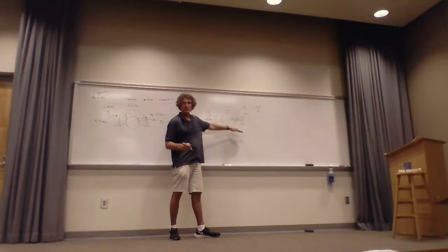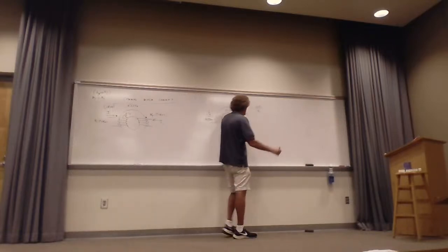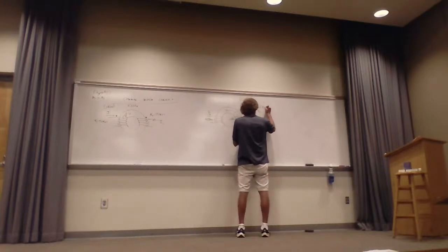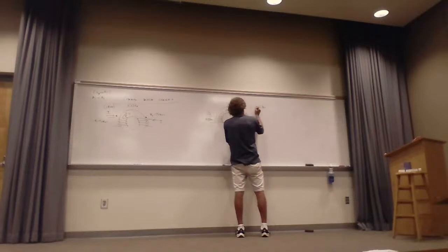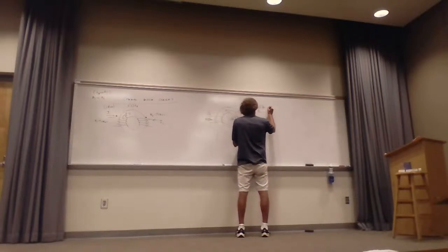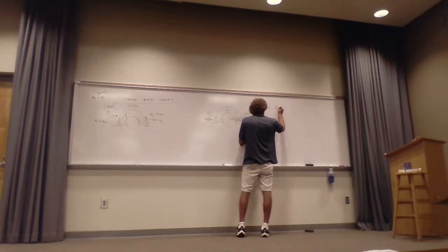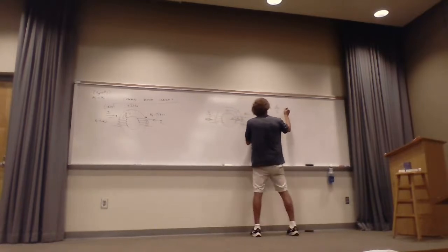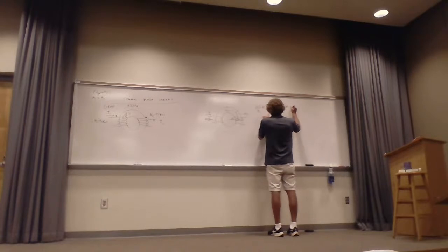That's the flux through one. There's nothing connected, no load out here. So now I multiply it by N2, and that's the flux linkage. When I divide it by the current causing it, I get the mutual, which is N1 N2 divided by the reluctance.